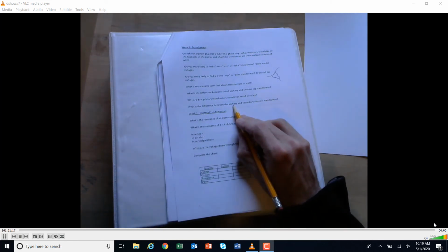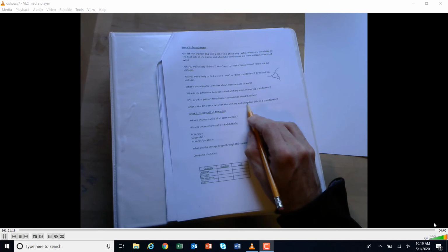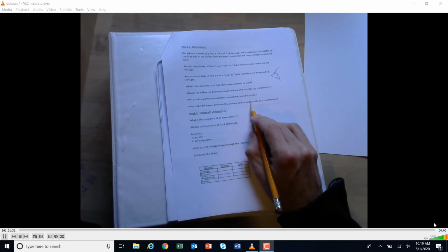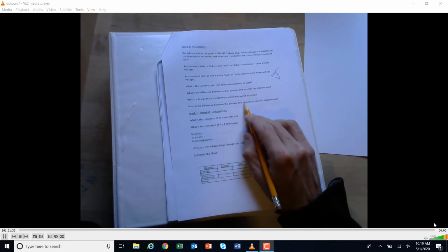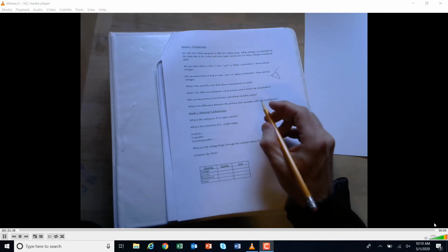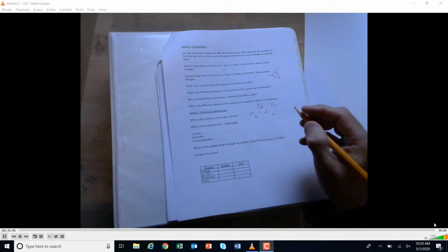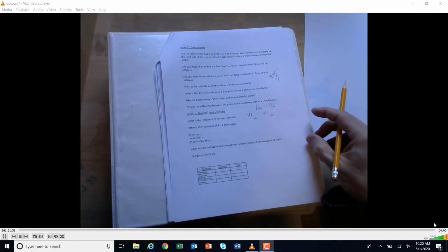In the primary and the secondary side, primary is where you're bringing in your voltage, and the secondary is the voltage that you wanted conditioned, usually brought down to the level that you wanted for a control circuit. So you brought in 208, and then you wanted 120. That would be your secondary. We talked about the turns ratio, and that the power in equals the power out. Or to say it again, the VI in equals the VI out, right? Volt amperes in equals volt amperes out. We did some calculations on that on the transformer.